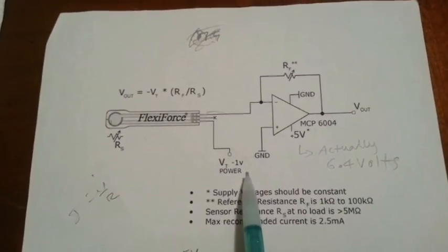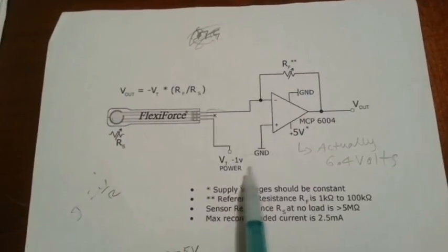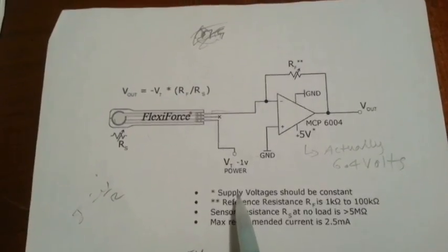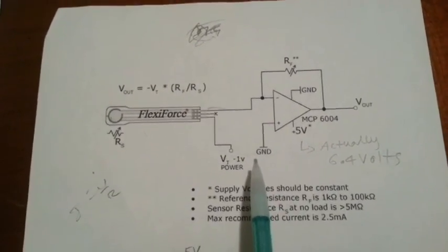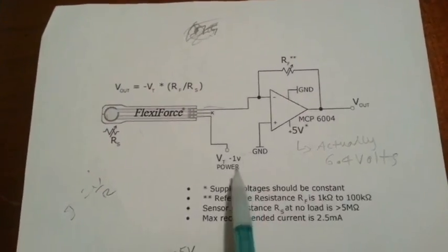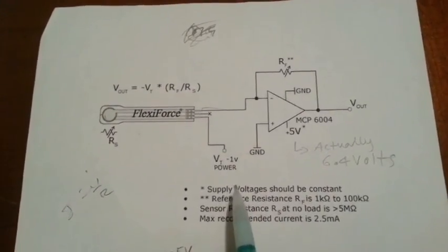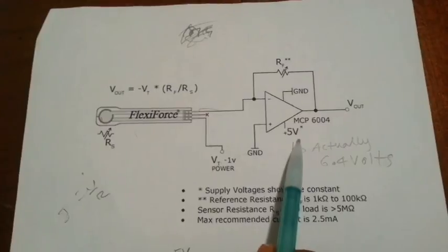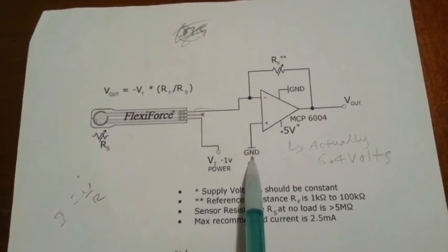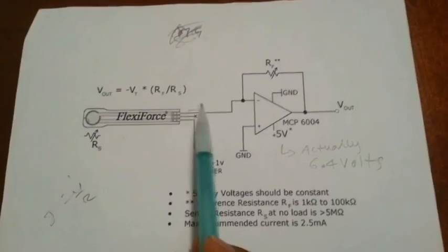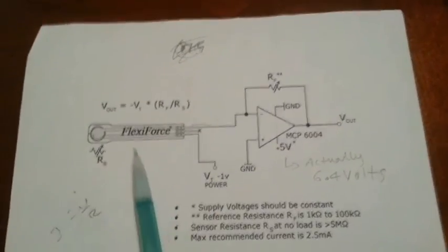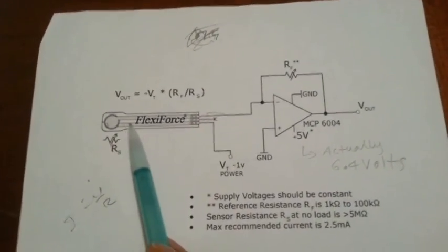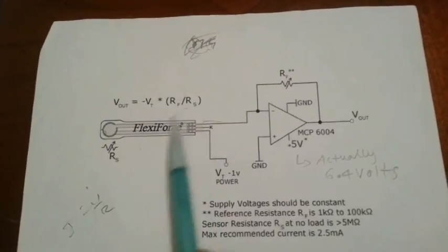The particular op-amp that we used is the LM324N. After doing research and experimenting, we found out that that was the best op-amp to use for this application. One of the advantages that it has is that it can be powered by using only a single power supply, which is 5 volts, and using this configuration no RI is needed. The reason for that is because as force is applied to the sensor, the resistance actually goes down, which acts like a voltage gain.